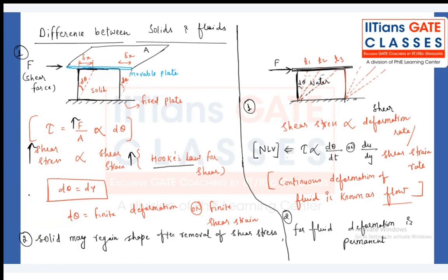Now, my friend, if I remove the shear force, will the solid be able to regain its original shape and size or not? If the deformation is within the elastic limit, definitely if I remove the load, the solid body will regain its shape and size. But if you deform it beyond the elastic limit, that means you are in the plastic zone, then you may not be able to regain its original shape and size.